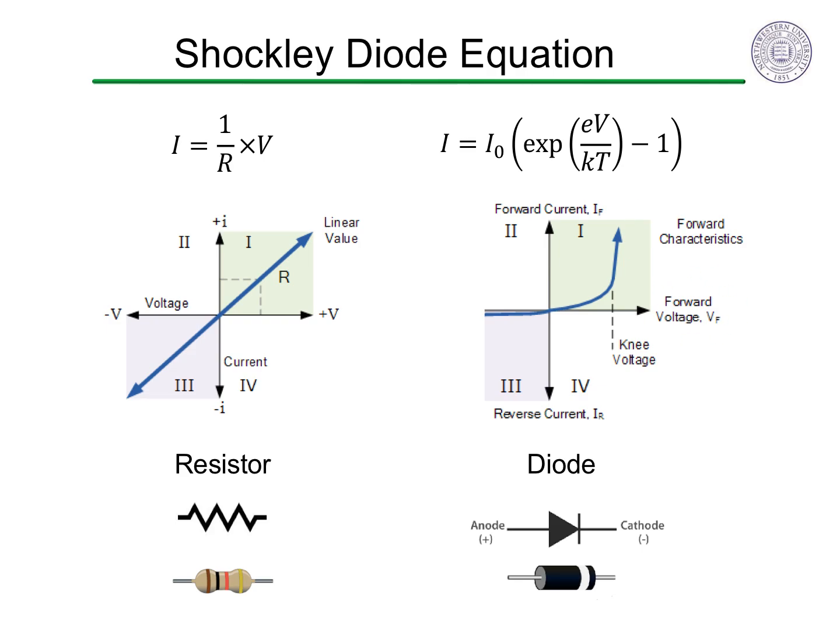If the opposite voltage is applied, the current in the direction of the reversed voltage is very small, usually too small to run a device. For most of this reverse bias, the current is essentially I0, called the reverse saturation current. Thus, a diode effectively only allows current to flow in the forward but not backward direction. The PN junction breaks the symmetry of a simple conductor.